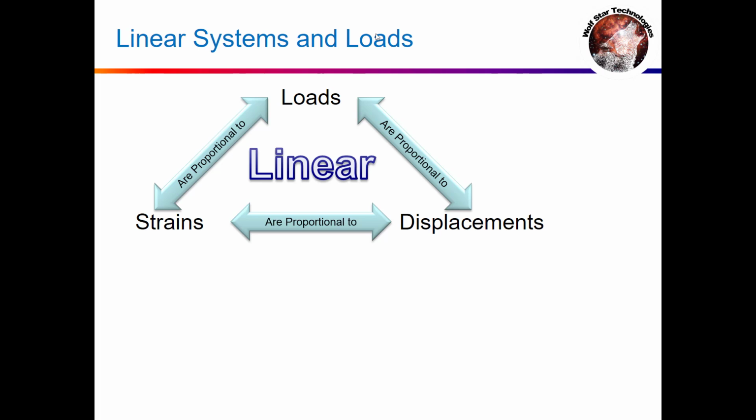We need the strain response to remain linear. Okay? The loading can be as nonlinear as anything. The loading could be sinusoidal, it could be ramp loading, it could be impact loading. That doesn't matter. I just need the strain response to be linear.